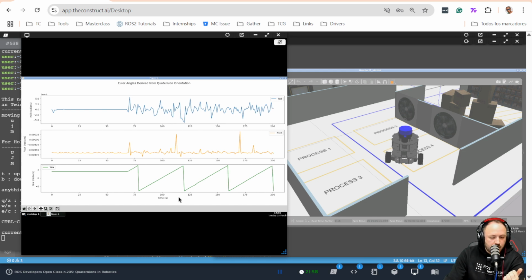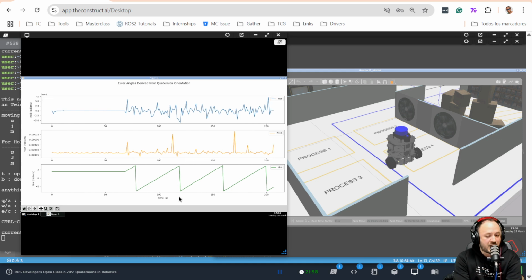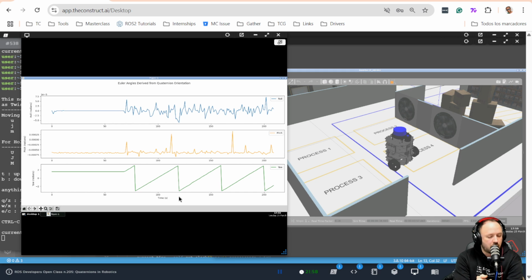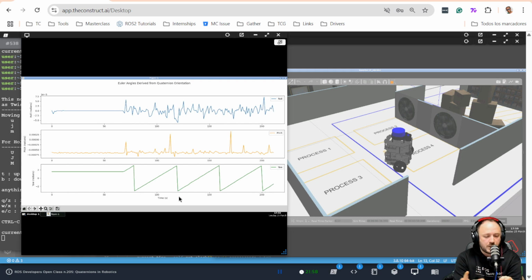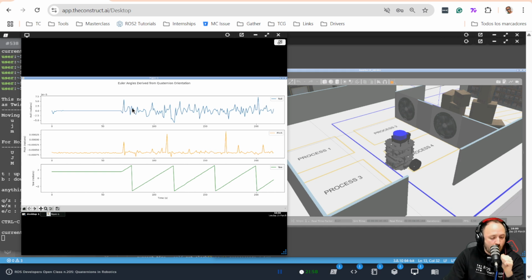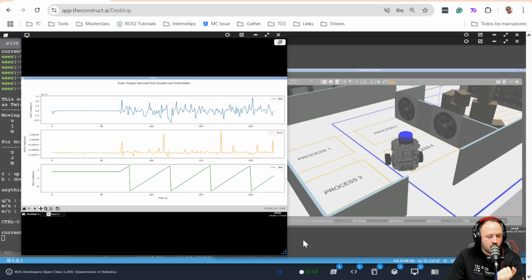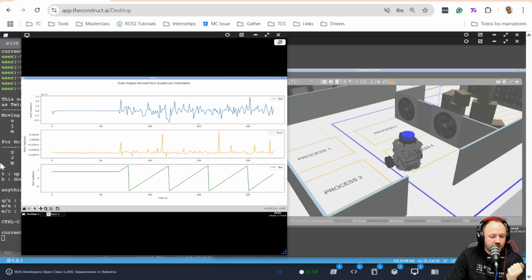If you happen to have a manipulator simulation, you can test it with that, or a drone simulation, for example, an aircraft simulation. You can use this to try to detect this gimbal lock and see what happens, how the system behaves and becomes erratic when one of those singularities happens.